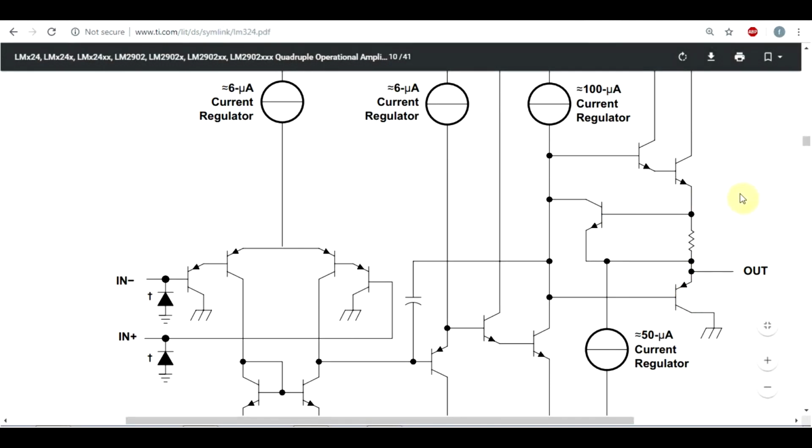Likewise, if you're using a certain current, not exactly the one that is the limit, but also not zero either, the voltage drop on the various components will be dependent on the current. So for every PN junction, the voltage drop will be somewhere between 0.5 and 0.7 depending on the current. And on certain output stages like this one, we've got an overcurrent limit protection.